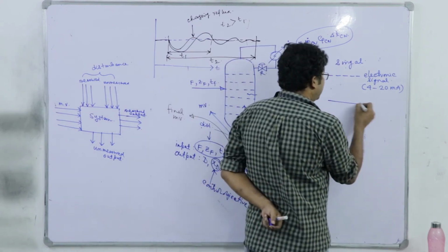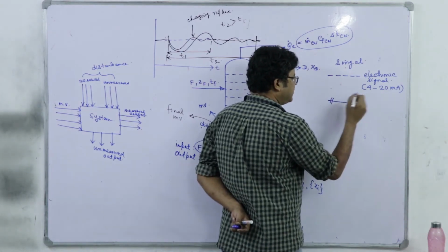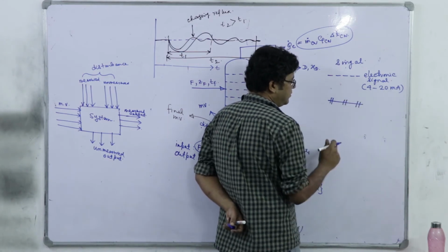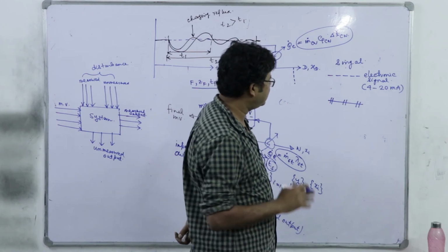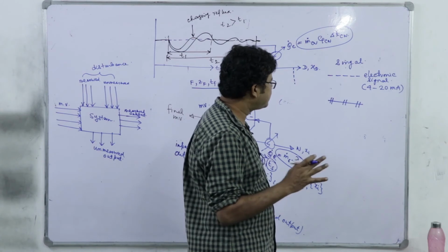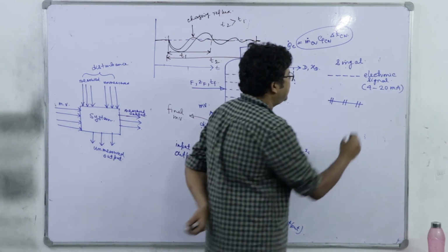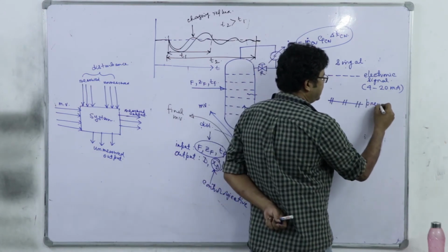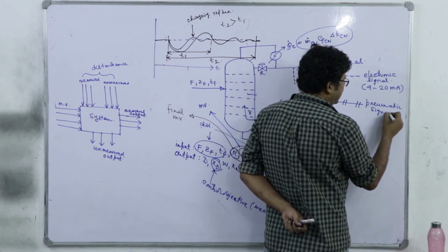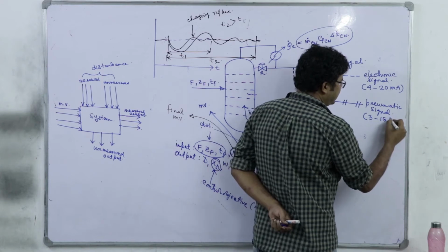And the next, in older process industry, when electronic signals were not developed, but still we use it for some purposes, we will discuss it. So, if I represent the information flow or the signal flow by this type of scheme, this is typically representing a pneumatic signal, right, with varying air pressure. And what is the pressure? 3 to 15 psig.